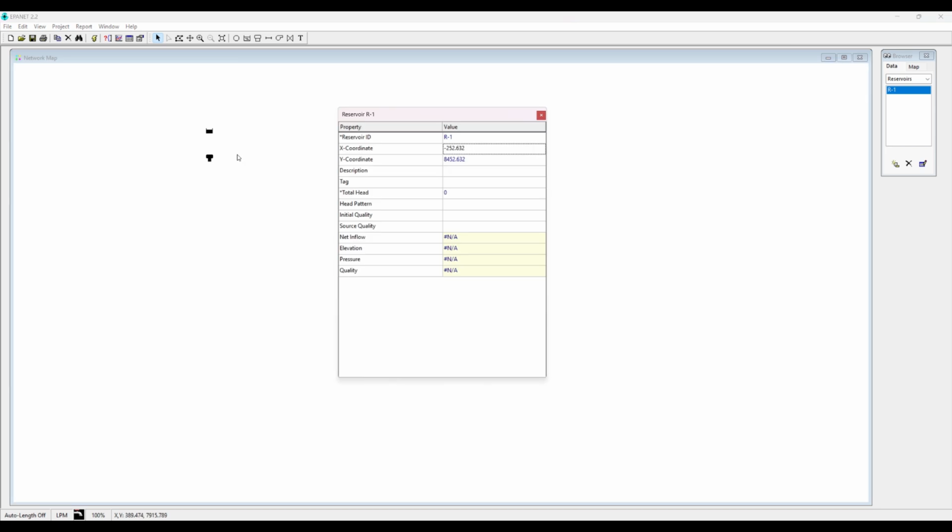A reservoir in EPANET, excuse me, always has, just like we assume in problems typically, no pressure at the top, right? Atmospheric pressure, it's not being contained. And really, a reservoir in EPANET stays at a constant level. It assumes a very large reservoir, so you're not going to drain out your reservoir.